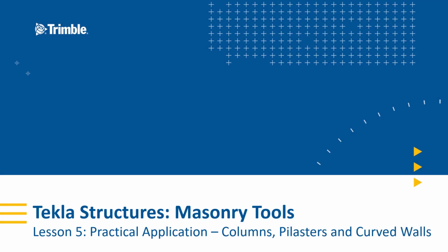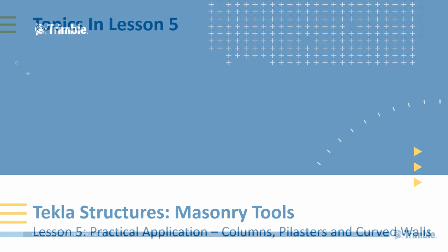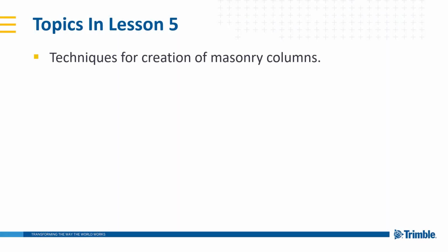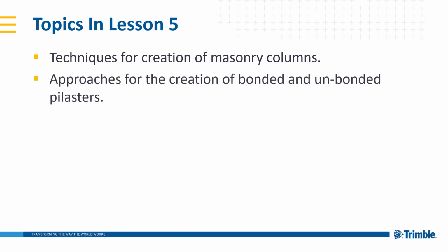Tekla Structures Masonry Tools, Lesson 5, Practical Application with Columns, Pilasters, and Curved Walls. Topics in Lesson 5 include techniques for creation of masonry columns, approaches for the creation of bonded and unbonded pilasters, and the creation of curved masonry walls.